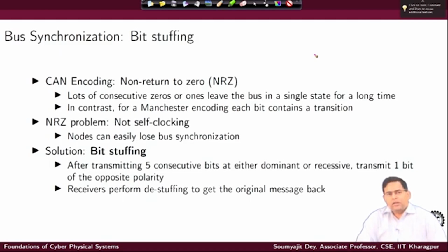So that leads to this whole problem of synchronization. But coming back here, let's just restrict ourselves to the understanding that for long periods, if there is no clock edge happening on the bus, there is no switching activity, the individual nodes may lose their synchronization with the bus. That means they will be unaware of the exact times when one cycle of transmission starts or ends in the bus. That is why, to break out of this issue, this rule exists. Okay. Now, of course, this stuffed bit needs to be understood. That means the protocol will also do suitable destuffing of this bit from the original message at the reception side.